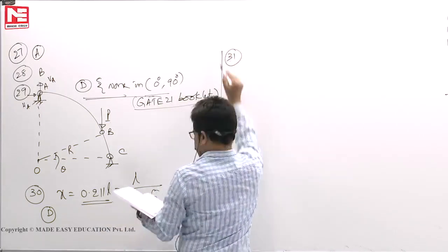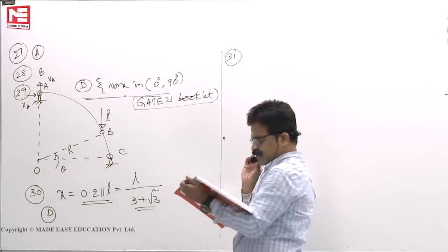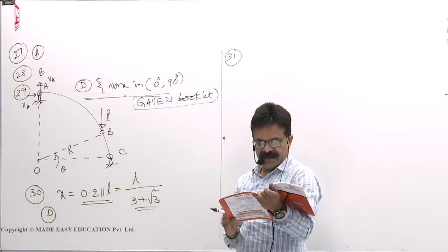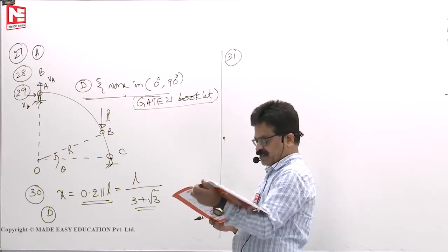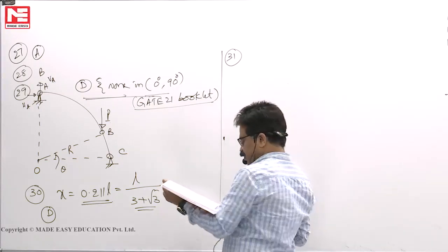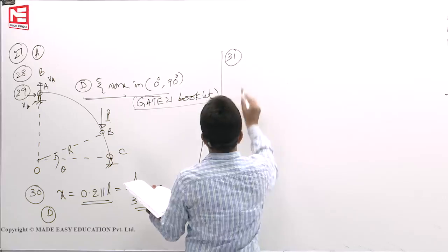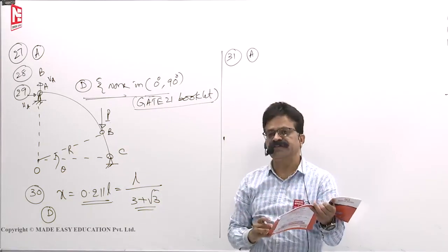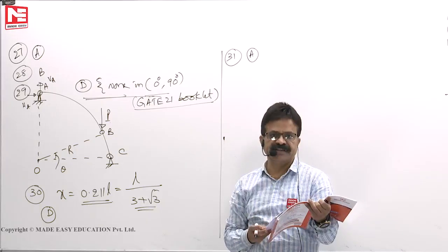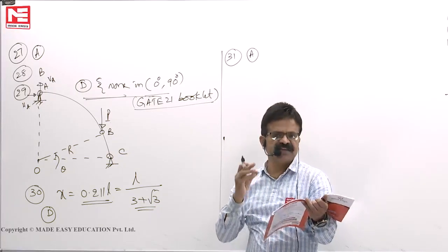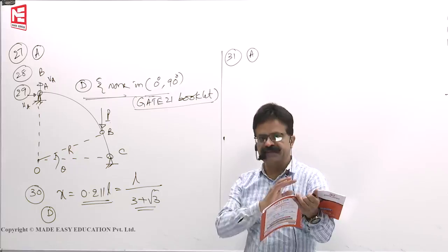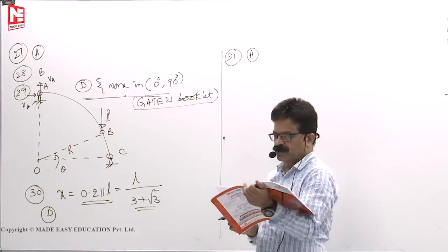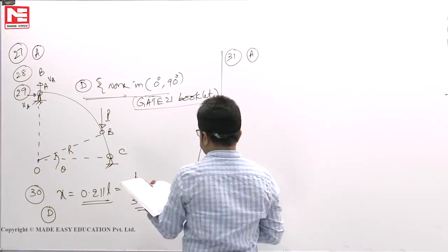Next, 31. Which one of the following is associated with the rib shortening in arches? This same question is repeated. Only 2-hinged arches and not 3-hinged arches, because in 3-hinged arches rib shortening will not happen, because no temperature rise or sinking or yielding or fabrication errors will produce any stresses. Okay. So over. Next, 32.